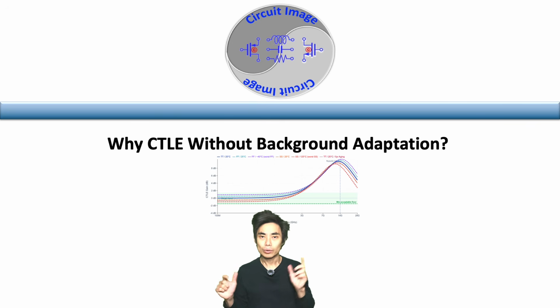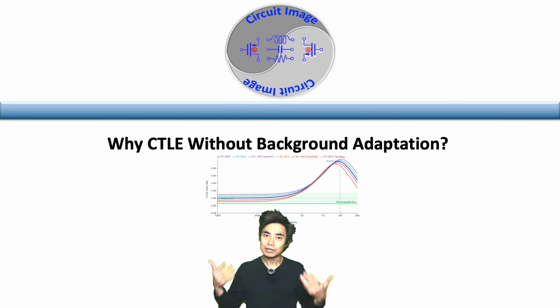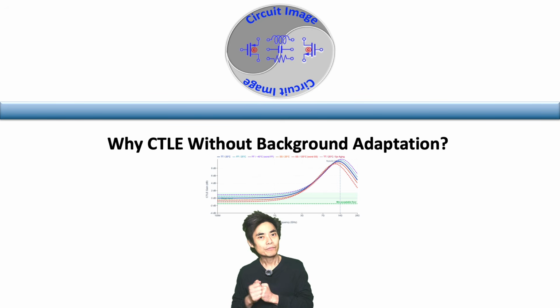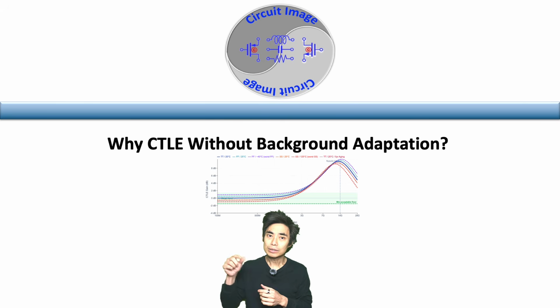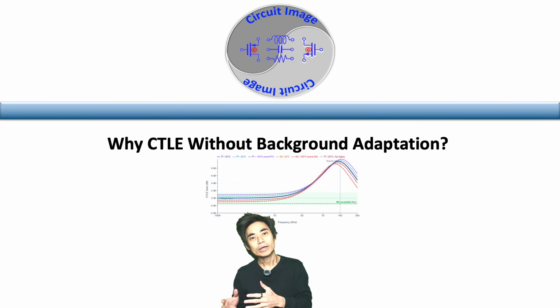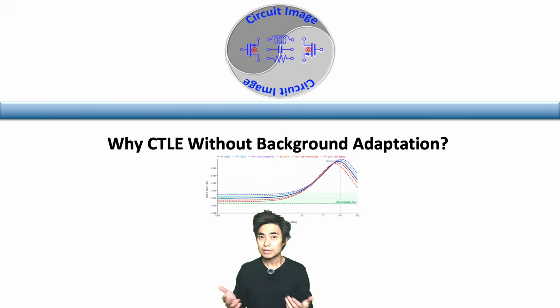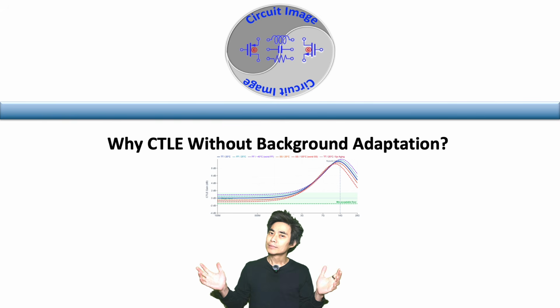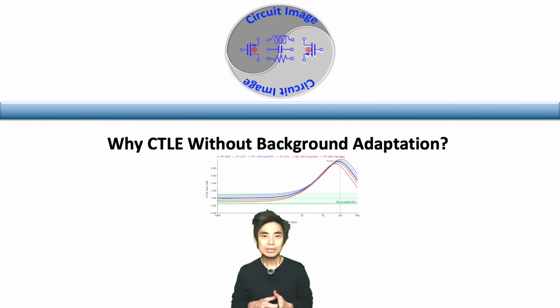Switching resistors or capacitors in a live continuous-time signal path injects charge, shifts the bias point, and moves a pole instantly. In PAM4 systems, a small analog disturbance can ripple into slicer error, DFE confusion, or even CDR instability. So the real question isn't why not adapt, it's can we design the CTLE stable enough that it doesn't need